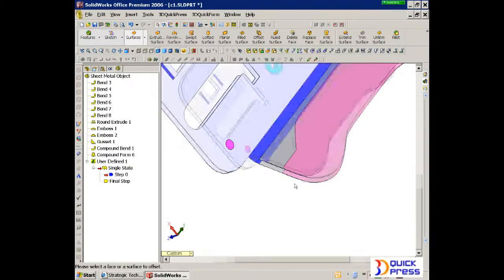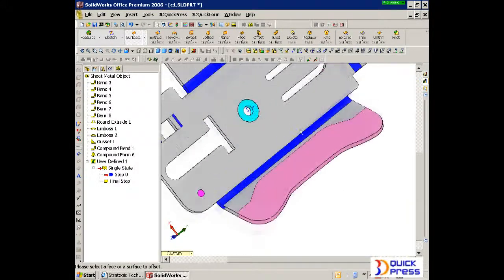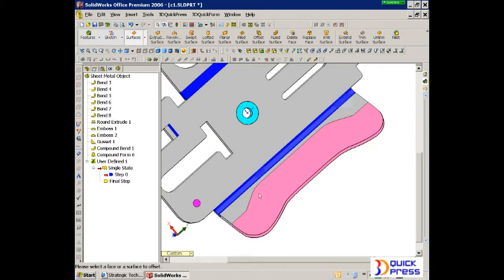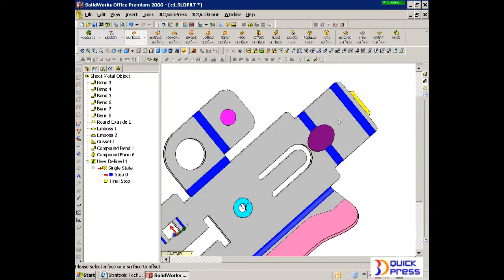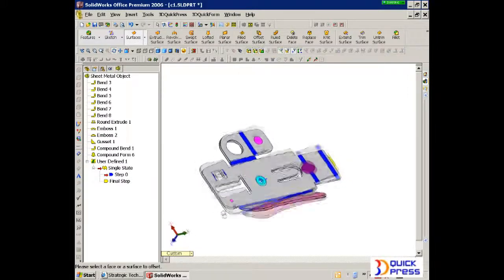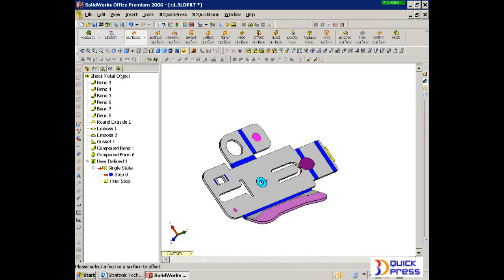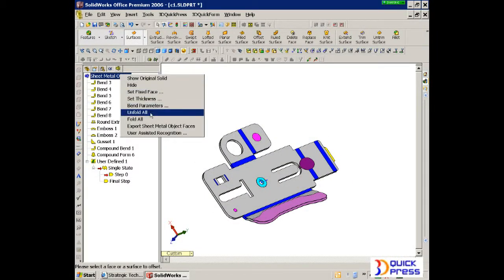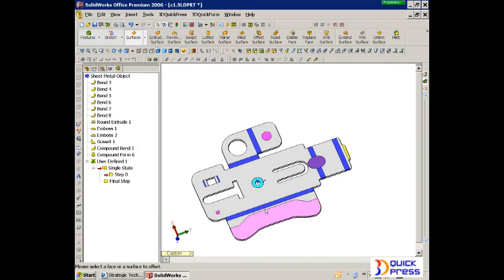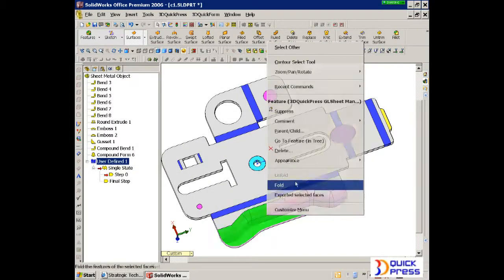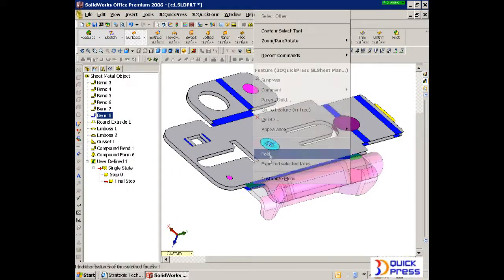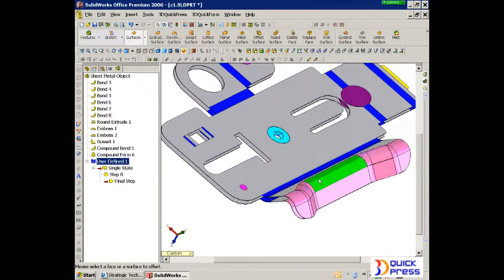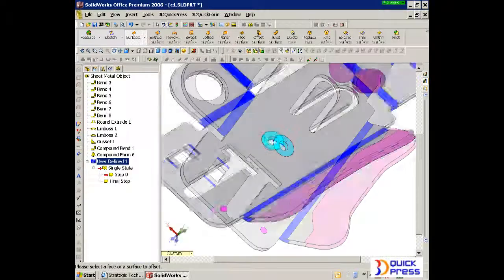So this is a very good case where you can quickly do an accurate blank prediction but still maintain analytical information such as bends and localized and regional issues, so you do not have to blank the whole part and then try to recreate it in the strip. Alright, so now we can see that we can take this and go through multiple stages. You notice the form with the blank, and then we can fold that up and it's still formed, and of course we can keep on going through the different iterations.